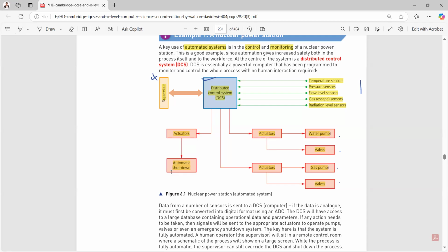लेकिन इसका सॉल्यूशन ये होता है कि जब मैंने सेंसर सेट कर दिए और वो रीडिंग पे आ गया, 50% पे वाटर आ गई, 50% पे गैस आ गई, तो सेंसर माइक्रो प्रोसेसर को अलर्ट करेगा कि ये वैल्यूज हमारे पास हो गई हैं। फिर माइक्रो प्रोसेसर एक्चुएटर को कमांड देगा कि अब आप इसको क्लोज कर दो। और ये सारा काम सुपरवाइजर एक जगह बैठा हुआ देख रहा होगा। माइक्रो प्रोसेसर का काम है मेंटेनिंग द होल सिस्टम, कि कोई भी वैल्यू जो मैंने सेट की है उससे ज्यादा नहीं जाए।